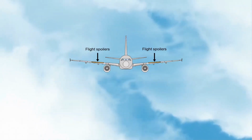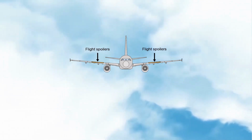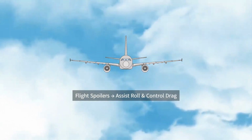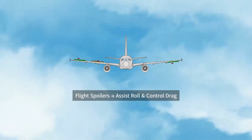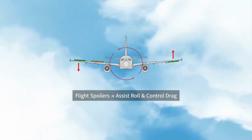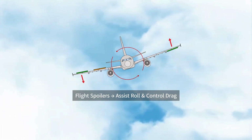Flight spoilers, on the other hand, can be extended in the air. They serve multiple purposes. Most notably, they assist with lateral control. For example, when an aileron on one wing is raised, the spoiler on that same wing may also extend. This increases drag on that side, helping the aircraft roll more effectively.